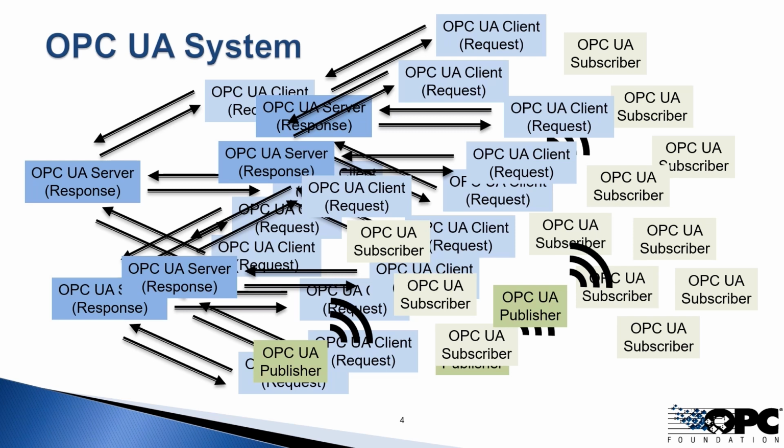So again, using the example of each server storing its own usernames and passwords for the same users becomes a maintenance nightmare for an administrator who has to keep everything in sync, adding and removing users, updating passwords, and so forth. So it's for this reason that we introduced the optional centralized components to aid largely in the administration of OPC UA systems.